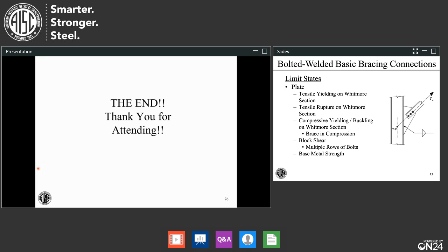Like, for example, you have these three braces coming in. The Whitmore sections may be overlapping between the three. It depends on which ones are in compression and tension, and with different load combinations, and so on. But no, I don't have just a prescriptive advice. Just lots of free body diagrams. Go look in Design Guide 29 and make sure you have the chevron stuff down pretty well.